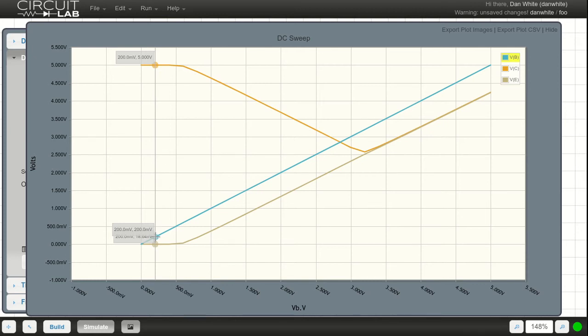If you do this specifically, to figure out what mode this is in at 0.4 volts, the emitter voltage is about 0, or 41 microvolts. So that PN junction between base to emitter, P to N, is forward biased. The PN junction from base to collector is reverse biased. That technically puts us into active mode, but we see that it behaves as if it's just shut off. There's no collector current, no voltage across the resistor. The collector voltage stays up at 5. So we call this cutoff.